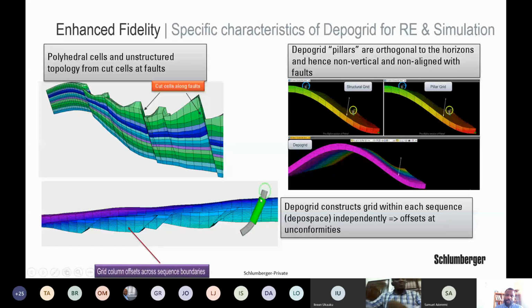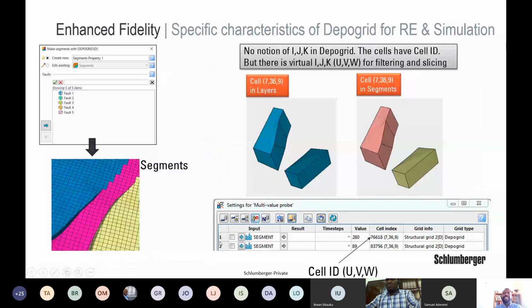Through that, we're able to model complex fault systems without having challenges in the simulation part. The other one is the fidelity, and this is important. So we're able to model different fault compartments. If you have a VBM grid, for example, you have here a zigzag according to the faults. If you have a pillar gridding, you have here the pillars defined.